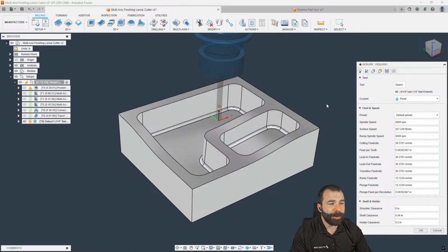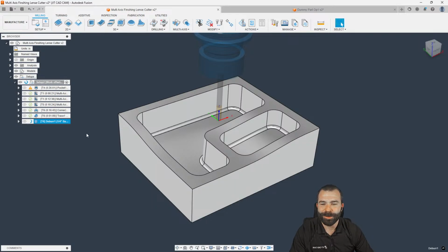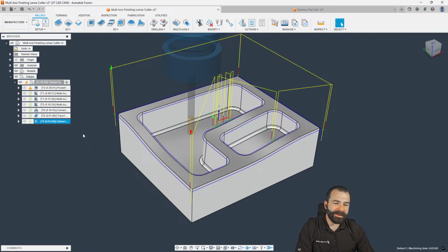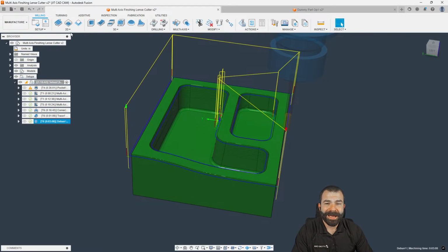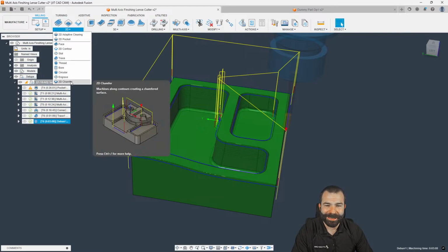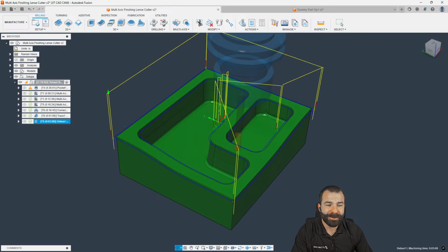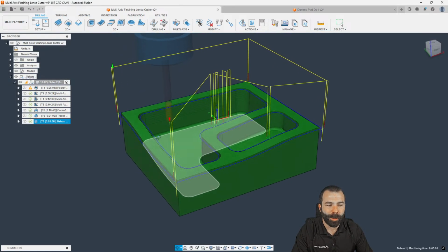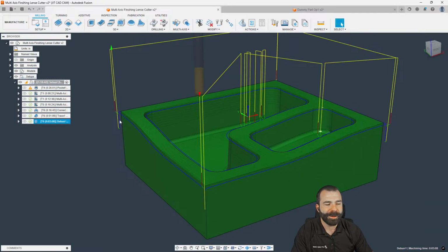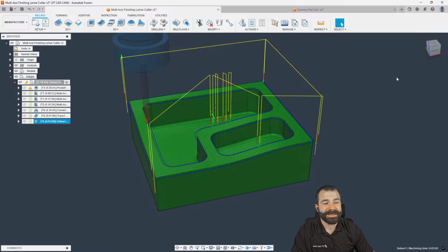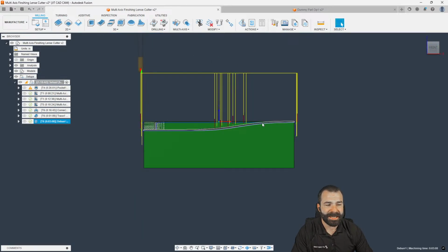Now, as you can see, I'm going to pull out the deburr toolpath, and this time I'm not going to be a fool. I'm not going to click a bunch of buttons because it's got me in trouble already today. Let's go ahead and hit OK and see what we get. This tends to be definitely one of my favorite add-ins to Fusion, and for many years, if you knew me, I used to say they should relabel the 2D chamfer to deburr, but I'm glad they didn't. Because with the new-ish deburr toolpath, you can now see how we can go in and actually find all of our edges, including our vertical edges here, which I'm going to show you how to avoid, and automatically find even something with some crazy surfacing, as you're seeing with the surfaces on my part here.